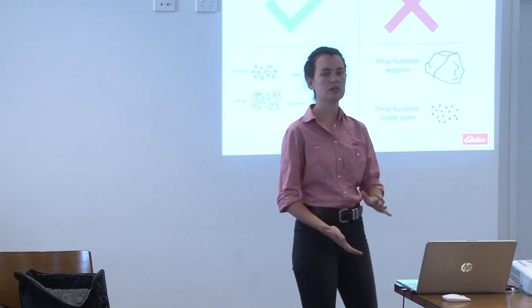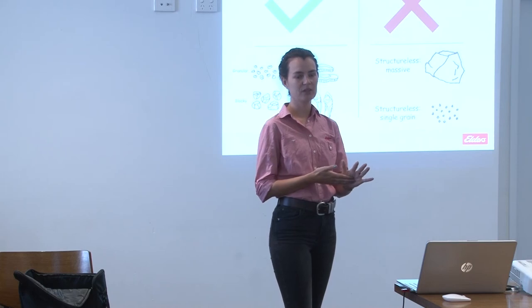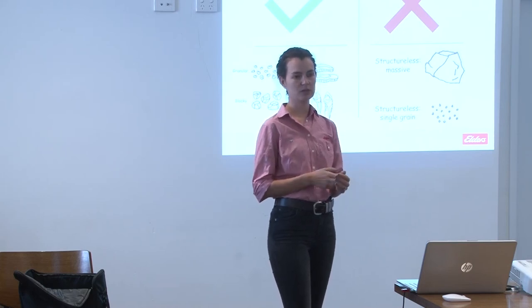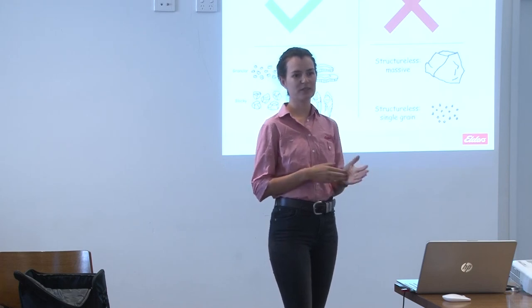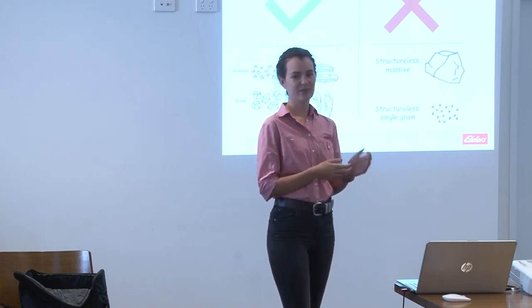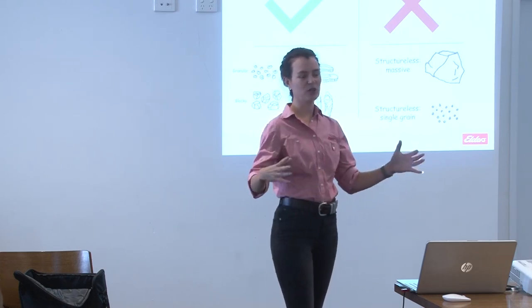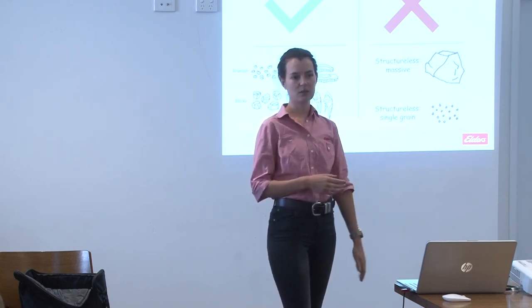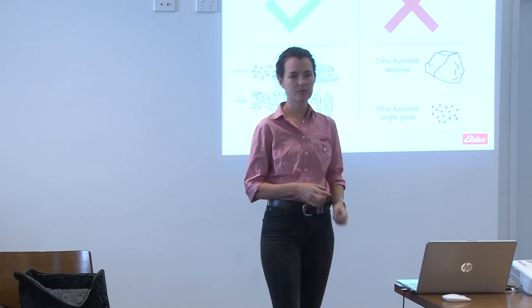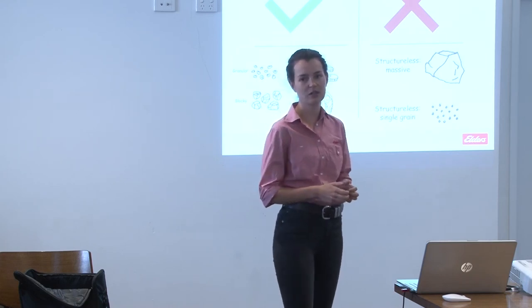I suppose the only other thing to touch on there is how to work out if you do or don't have structure. Upper North does have a penetrometer from a previous project. The only problem is it only works if your soil's at field capacity. Rarely do we get enough rain to get to field capacity, but you can put a drum out and fill it to get it to field capacity, then go out and measure. Essentially the deeper the penetrometer can go, the better your structure. Beyond that, it's a soil pit, which is pretty invasive and not everyone has an excavator.